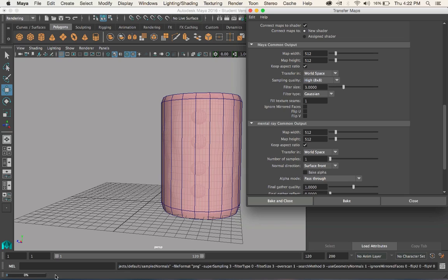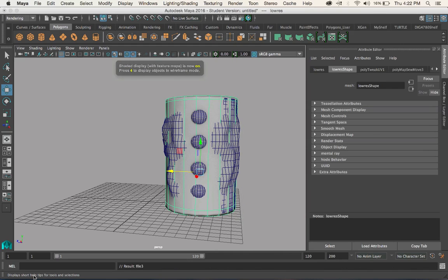It's going to run through the normals. Now it's going to go to mental ray and run through that process. And right now that mental ray process is going to be the, what's it called? The alpha channel, or pardon me, the occlusion map, sorry. And I swear I know what I'm talking about. So this is going to take a little bit longer just because it is running a special set of background items like your occlusion shader and so forth. But now what you'll see, and it's really quite amazing, it actually bakes that map into what you're looking for.